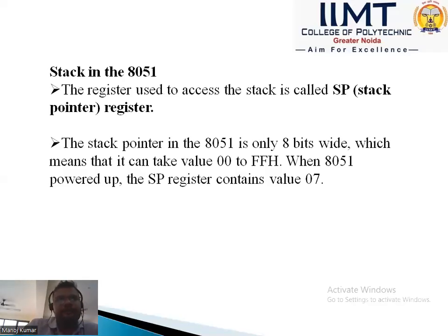The stack in the 8051 is accessed using the SP, the stack pointer register. The stack pointer in the 8051 is only 8 bits wide, which means it can take values from 00 to FFH. When the 8051 powers up, the SP register contains the value 07.